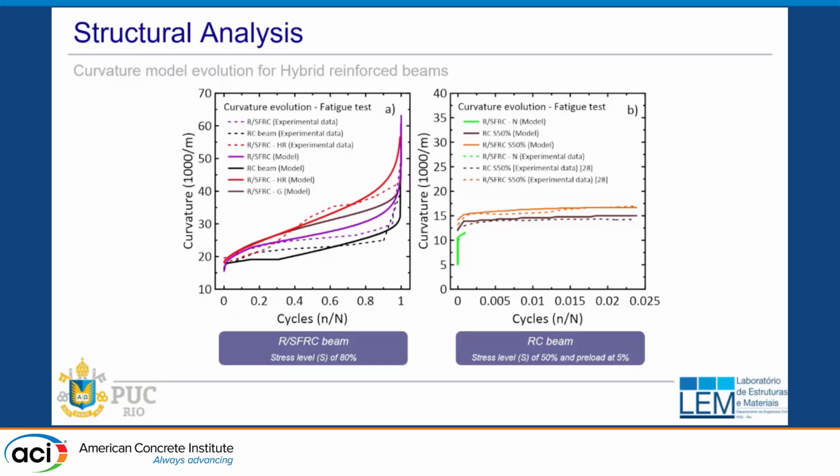We can do it for other types of fibers. It's not specific to the steel fiber, but it is a very positive way, in my opinion, to showcase that the best place to use fibers is for serviceability-based design, getting away from ultimate strength, because you can do that with our standard traditional methodologies.